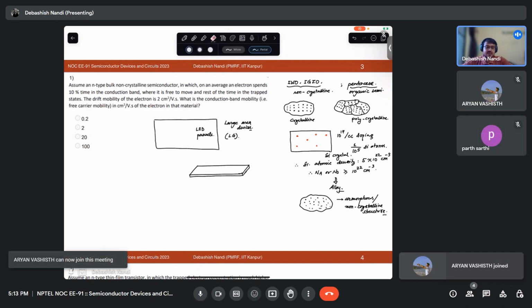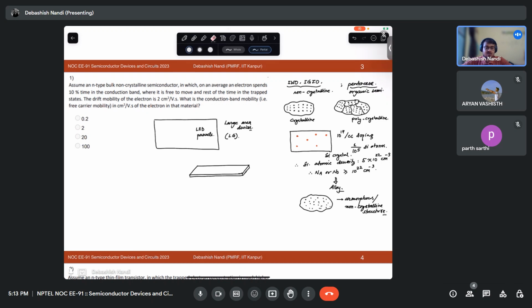the other thing is that you want to reduce the cost. These silicon wafers are very costly and the process is very costly. So for this LED kind of stuff, where you need to deploy some kind of circuitry through some kind of transistor action, you cannot afford to have silicon. So what they do is take glass substrates.